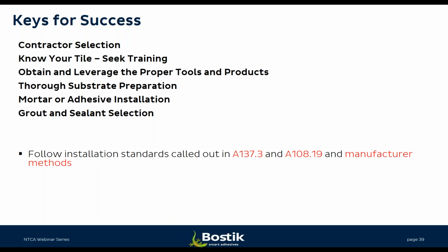Then the final would be the grout and sealant selection. This is also important. The grouts have a reason why we see the epoxies specified on floors in terms of their rigidity and their overall uber clean nature. And then the sealant applications for both floors and walls are an absolute must in terms of requirements for these installations.